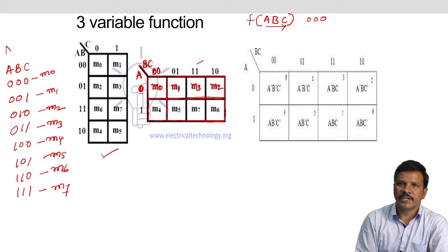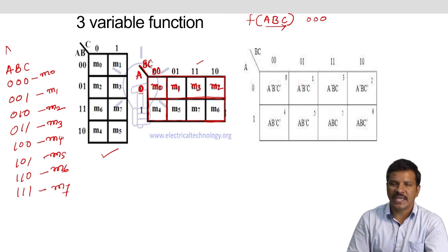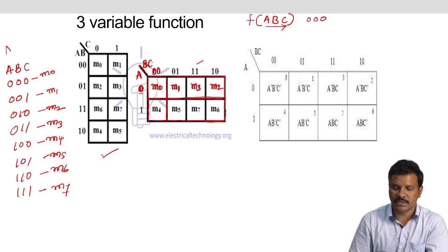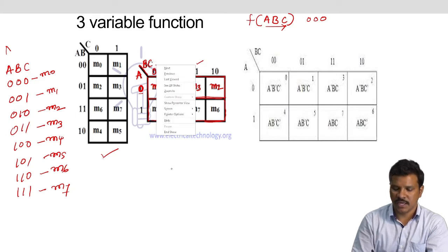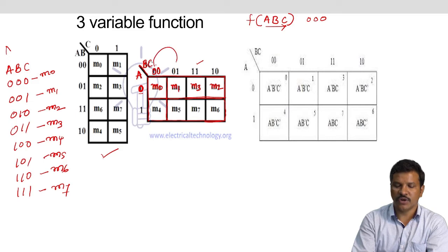As we see this sequence in the column, when we encounter this sequence of B and C terms, we cannot take the Boolean sequence 0 0, 0 1, 1 0, 1 1. But we can see here the sequence of this BC is 0 0, 0 1, 1 1, 1 0.